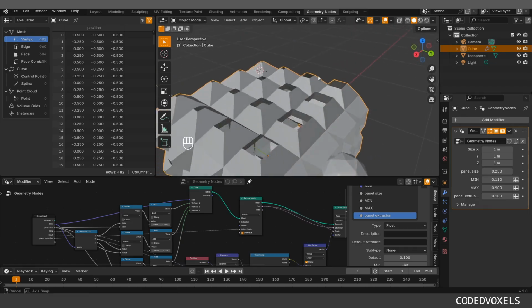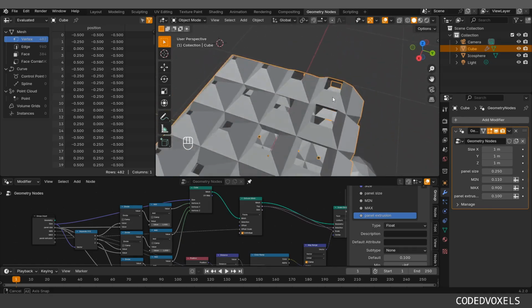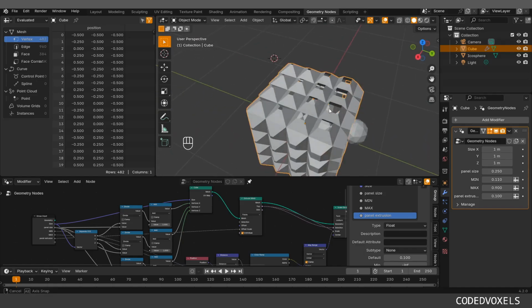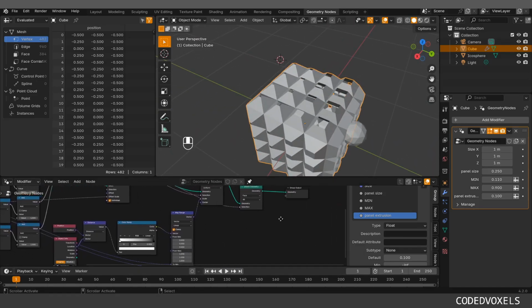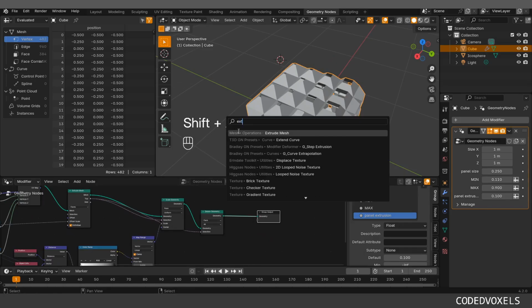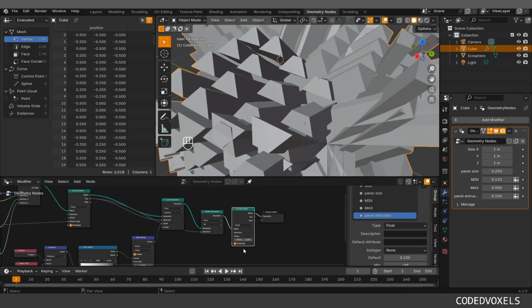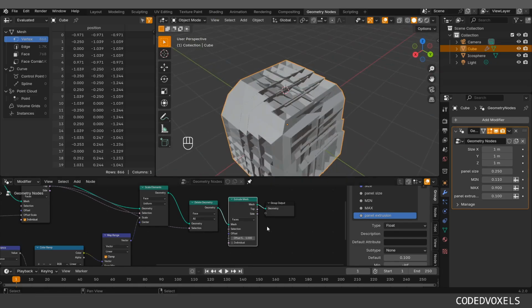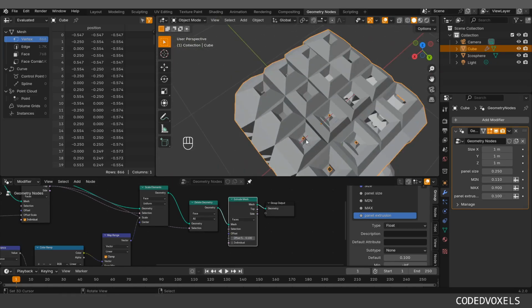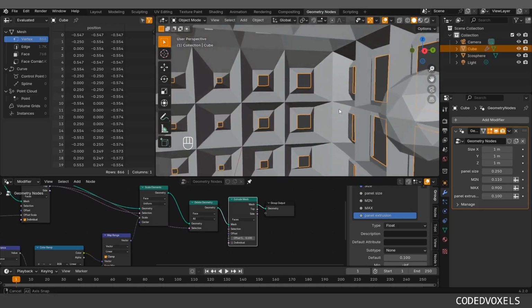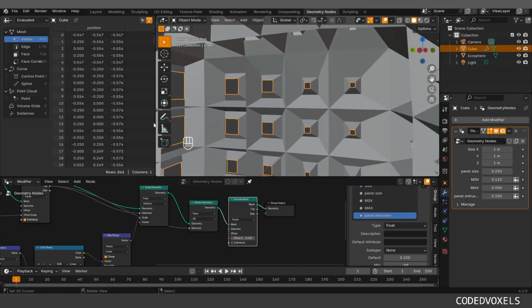And the first issue that you see is that it is infinitely thin. There's no thickness to it, and it's easy to see that that's an issue. So what I'm gonna do is I'm gonna kind of give it some thickness. So I'm gonna extrude mesh again. Whoa, not individual. That looks cool, but not what we're looking for. And then a lot less than that, so 0.1 maybe. And as you can see, we have this kind of feeling of thickness, but the issue is that that's only true from the outside, not from the inside.